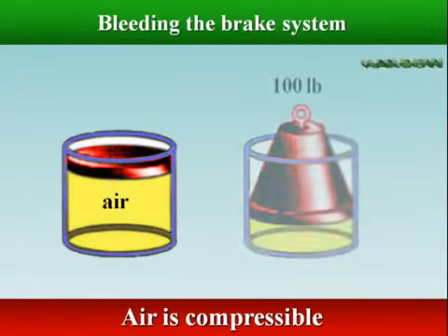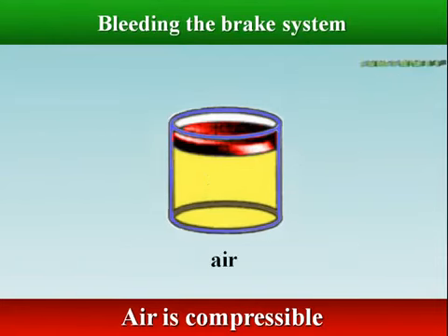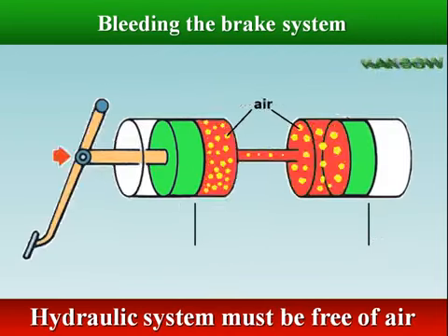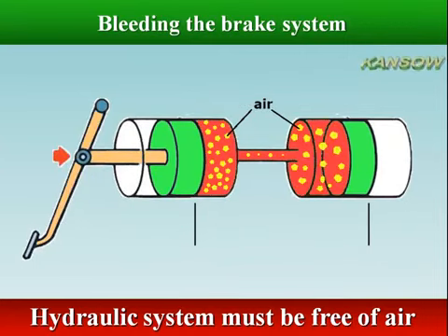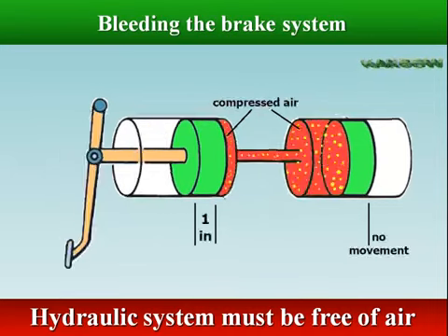Gases are compressible. Pressure applied to air changes its volume and some pressure is lost. A hydraulic system must be free of air to operate properly. If air is in the system, the air is compressed when the brake pedal is depressed, and the brake fluid does not transmit the force to the wheel brakes.